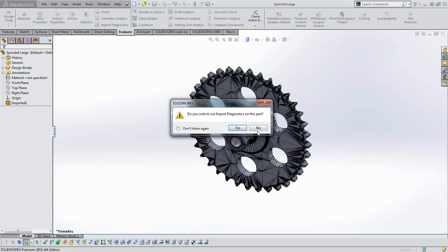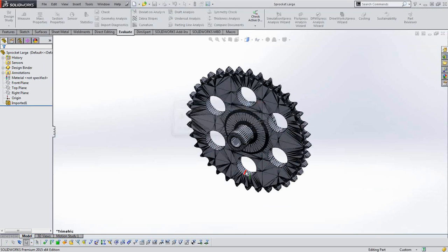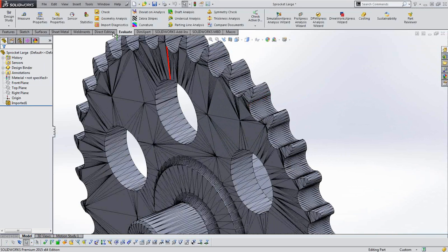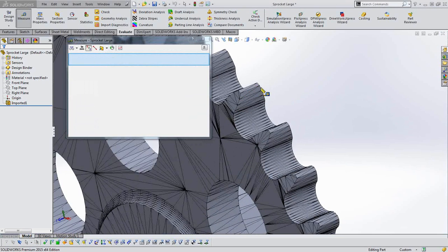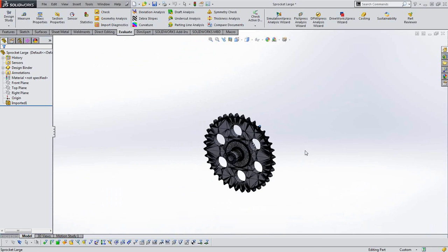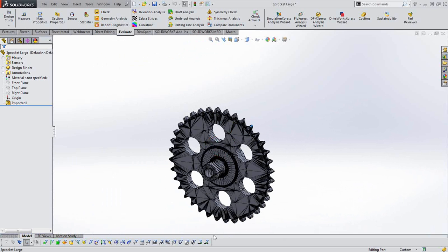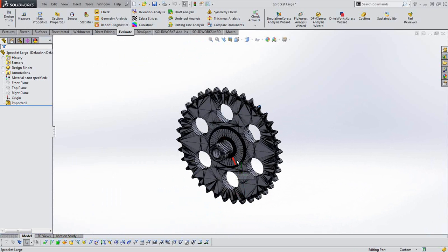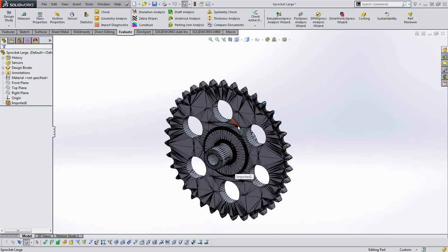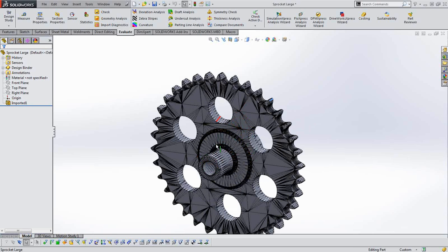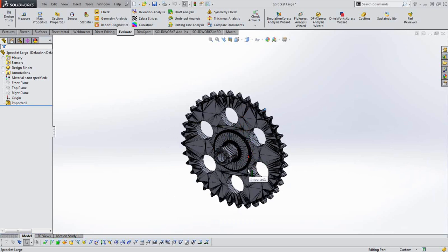This is where I prove to you that I'm not running a special version of SolidWorks. Mine crashes too. We're going to go ahead and measure that line again. And now all of a sudden we're 5.9987 inches. So the units that STL file was originally created in are very important. We need to know what those were, so that we create a part that matches those. You have to have your import units the same.